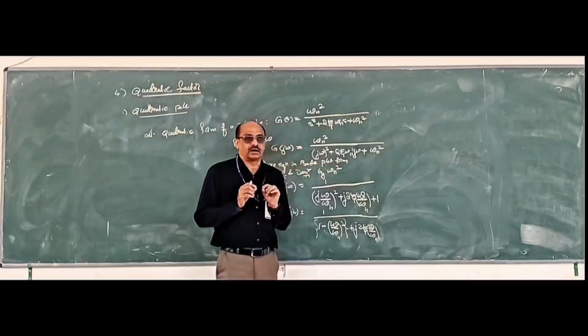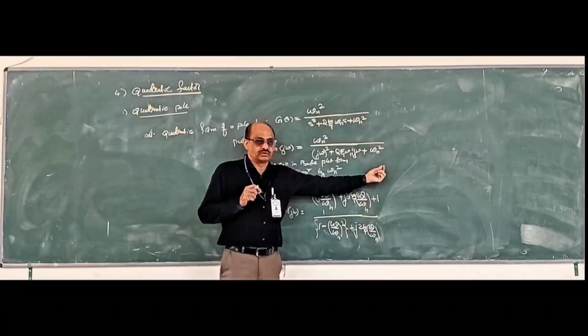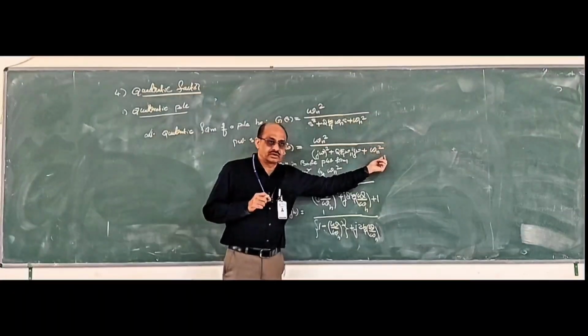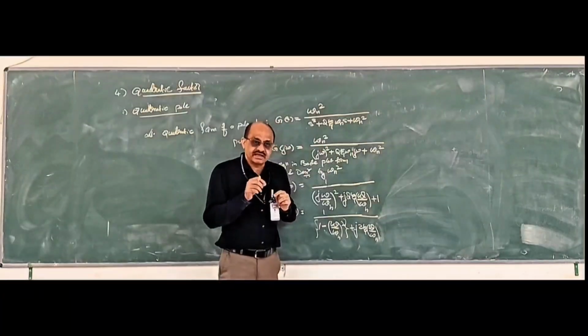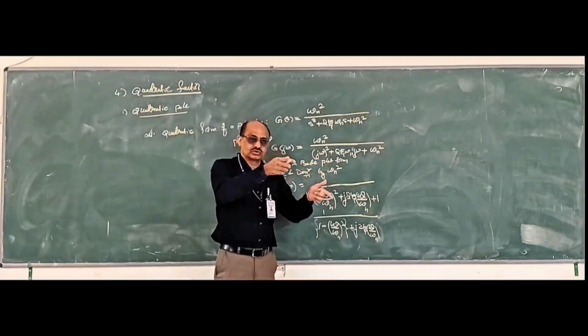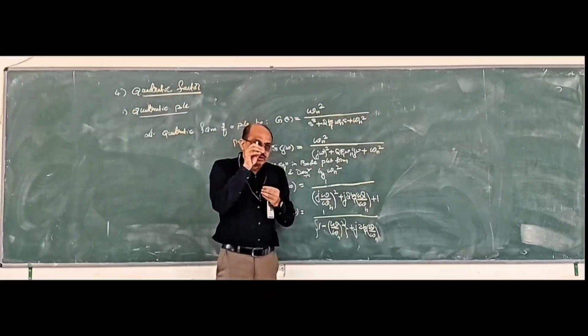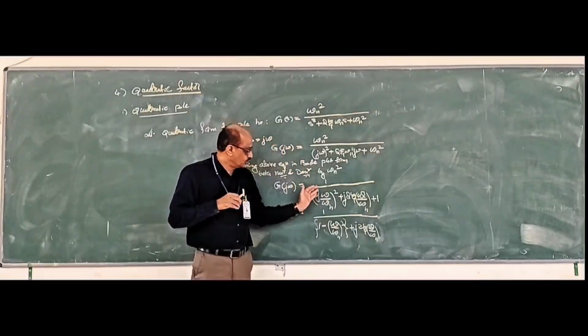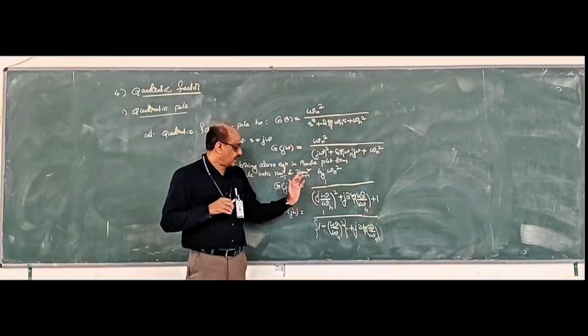Find what omega n square is. So you put it in the form of omega n square. If it is 100, say 10 square. If it is 4, it is 2 square. You have to write it. If it is 2, root 2 whole square, right? So root 2 is your omega n. You have to do that. So divide both numerator and denominator by omega n square.